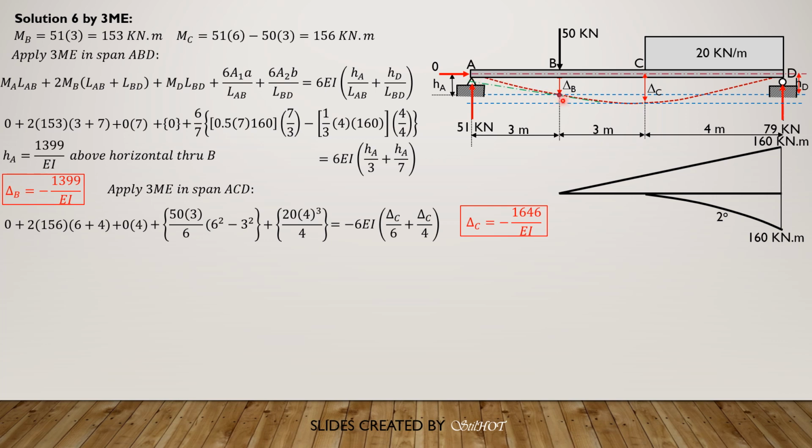Then if that is the case, the distance of point A from this reference tangent is the deviation of A relative to the tangent at B. Because this is the tangent at B, the angle that the tangent makes with the horizontal is the slope of B. So theta B is negative, because the tangent is rotating clockwise from the horizontal, right? So theta B is negative.